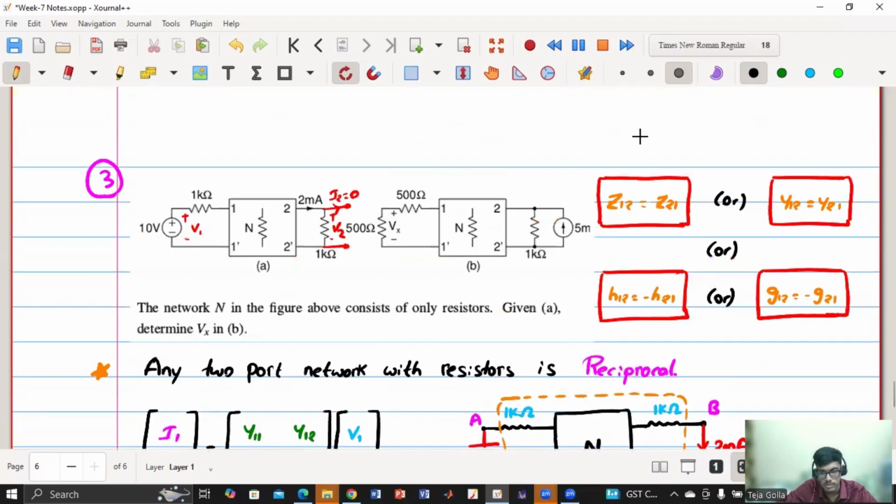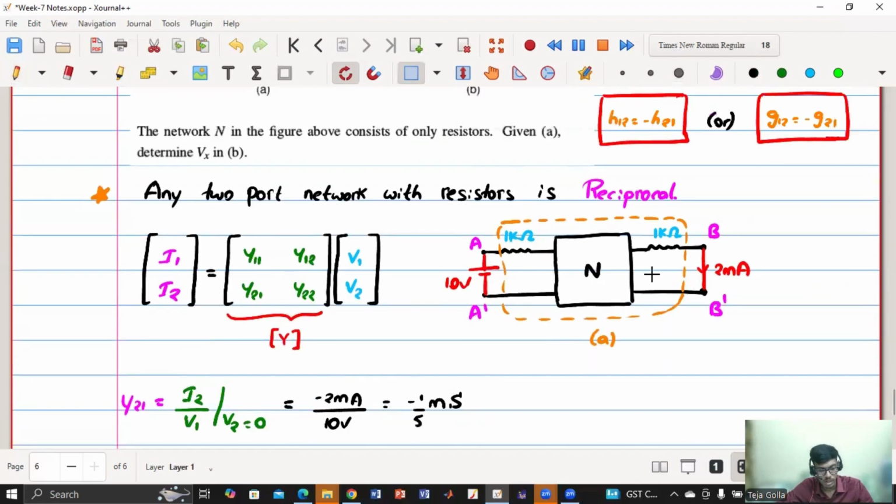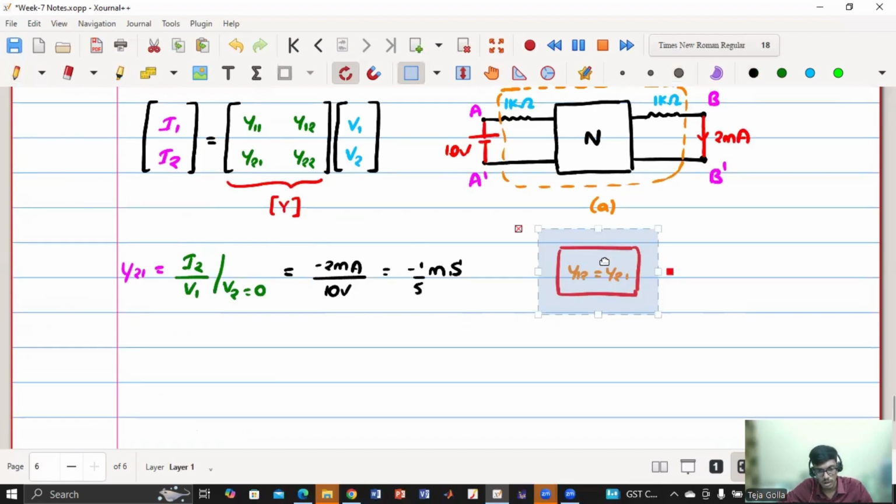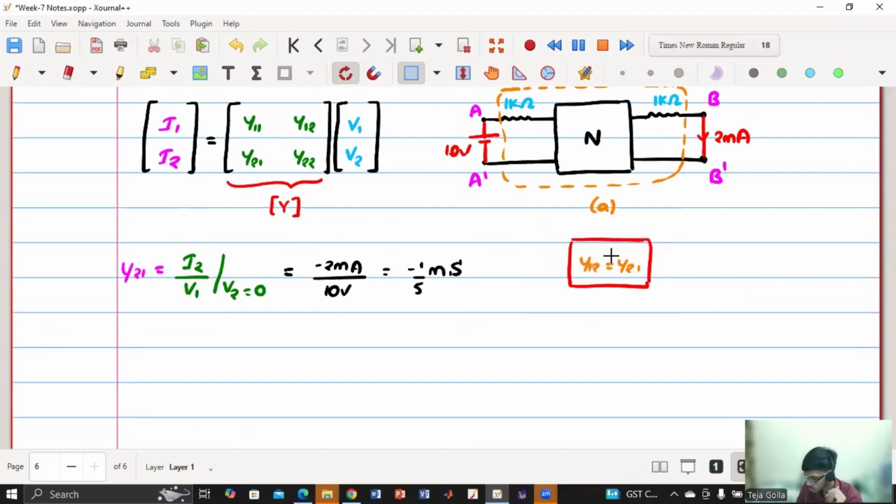Are you following? Yes, sir. So now because I have Y21 and I know I need Y12, what is my Y12? My Y12 is I1 by V2 when V1 equals to 0.